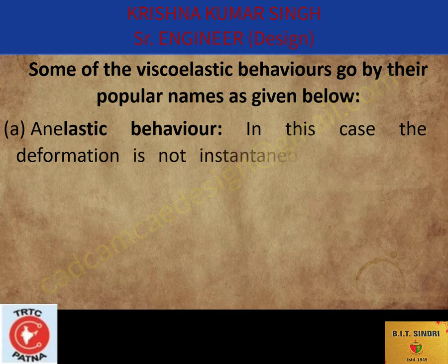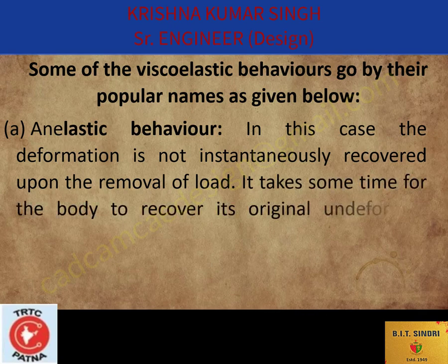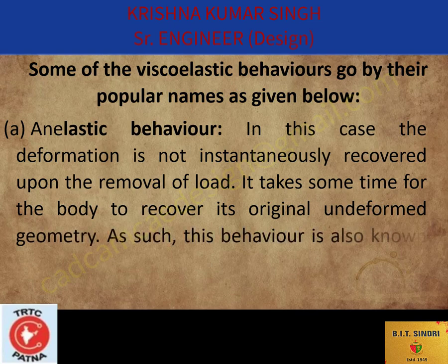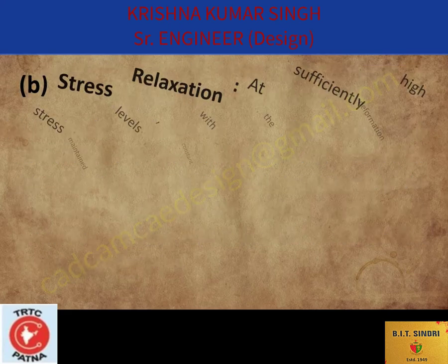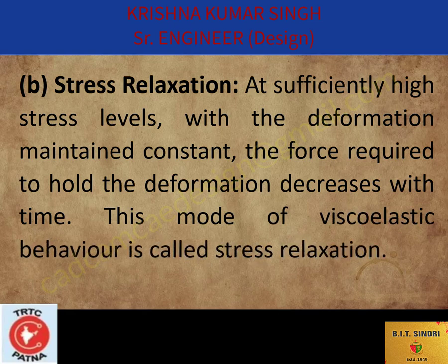First is anelastic behavior. In this case, the deformation is not instantaneously recovered upon the removal of load. It takes some time for the body to recover its original undeformed geometry. As such, this behavior is known as delayed elasticity. The second is stress relaxation. At a sufficiently high stress level with the deformation maintained constant, the force required to hold the deformation decreases with time. This mode of viscoelastic behavior is called stress relaxation.